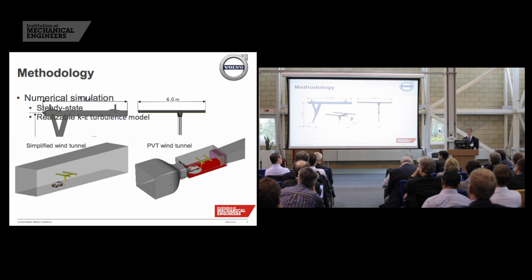And then you also have an arm, or a sting, to which the pressure probes are attached at the bottom under a 45-degree angle. Later on, I will distinguish between the effect coming from these wings and the sting in the further analysis in my results description.